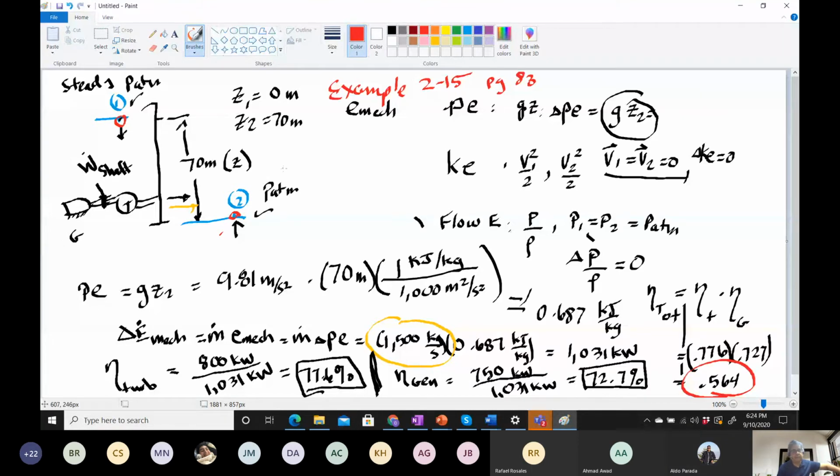They're open to the atmosphere, so therefore there's no pressure difference. That's not what's creating the flow, right? The flow coming out of the side of the mountain is created by something else. It's not pressure. Actually, there is a pressure here. If we measure the pressure there, obviously there's a huge pressure. Then we would just be transferring pressure with potential, right? So at that point, there would be no potential energy between this red point and point 2. It would be completely pressure.